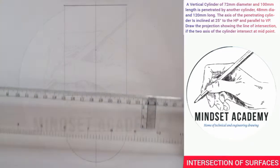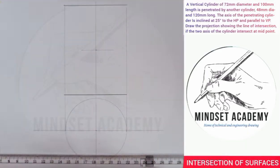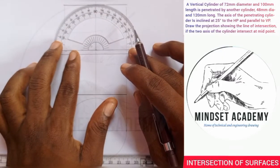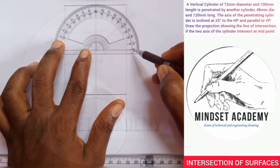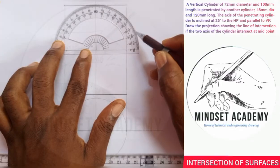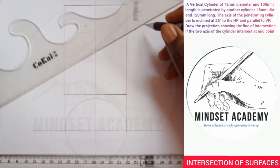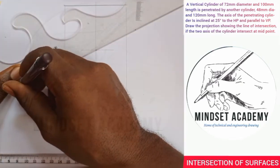So I'm going to draw my line this way, faint lines first, and we're told the angle is 25 degrees, so I can easily measure 25 degrees using my protractor. I'll place it at this point this way, ensuring that it is aligning with the line I drew. Measuring to the horizontal, this is 0, this is 10, this is 20, and this is 25 here. At that point, I'm going to use my meter rule and draw a line that will pass through the center here, in this fashion.